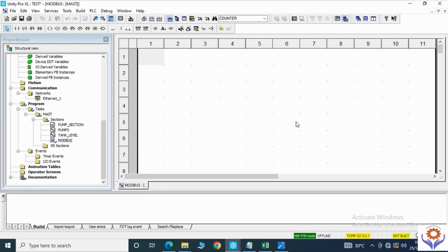If you have only one Modbus device, you can put read var directly, but here you have 3 devices, so you need to call the devices by scanning, like calling one device each 1 second. So I will put one counter.